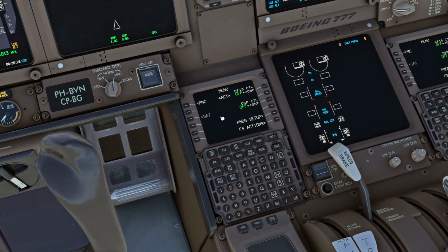So we're going to start off by hitting FMC, and the CDU will follow quite a logical order, so don't worry too much. It's going to be a bit overwhelming, but we're just going to take it step by step. You always start with the ident page, and here you can see the model of the airplane, the engine rating, the navigation data that's on board, and whether that navigation data is still valid. So as you can see, it is now active, and this is corresponding to the current date. So we're within these dates.